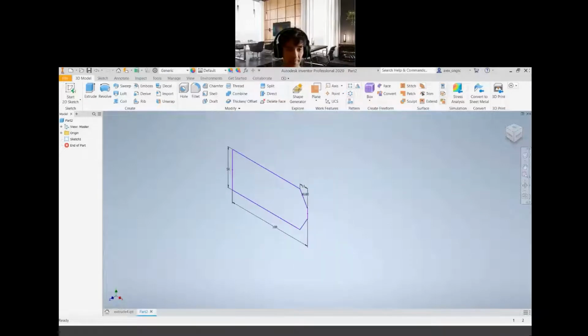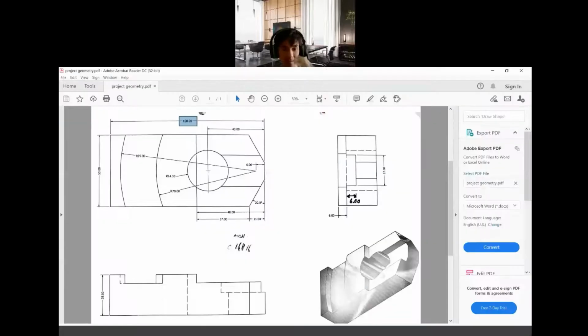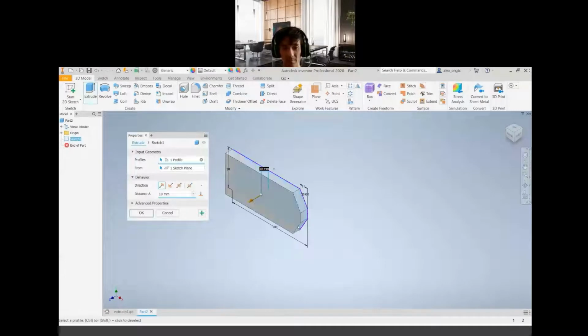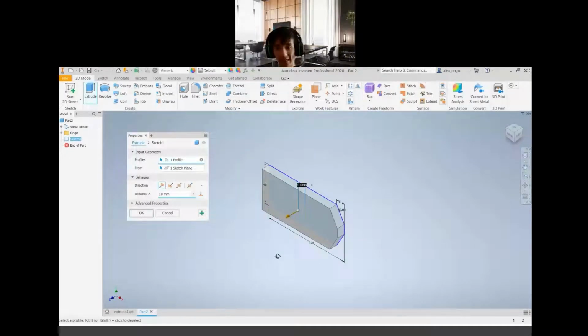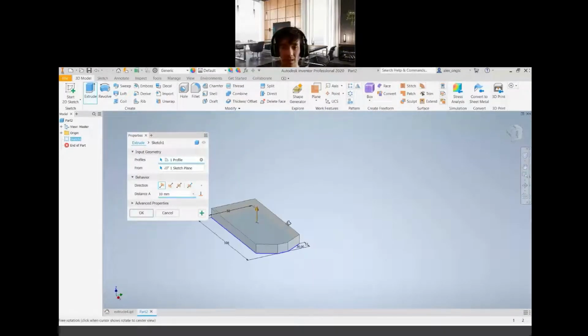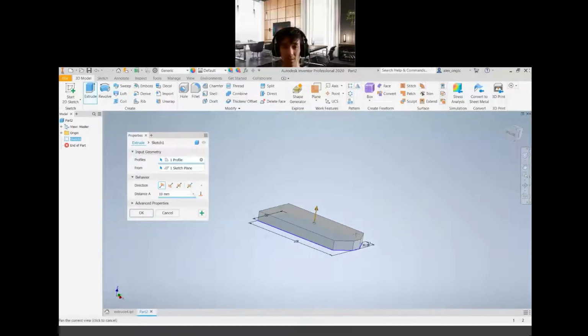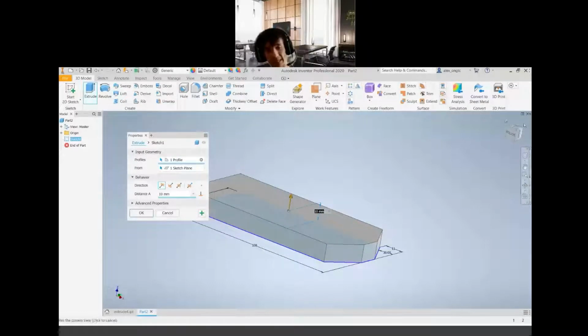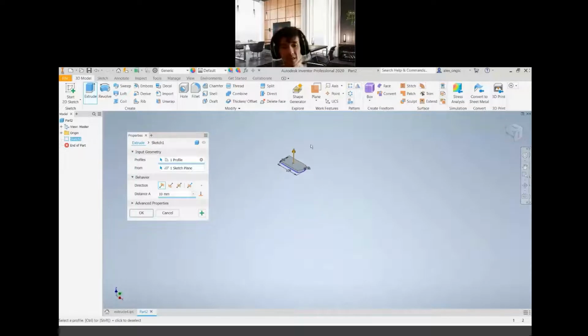Okay, what we intend to do with this, please do an extrusion so that you get these heights. Extrude up. We extrude the whole thing here to 20. So please go perform extrusion. Since there is only one profile of selection, it will be automatically selected.